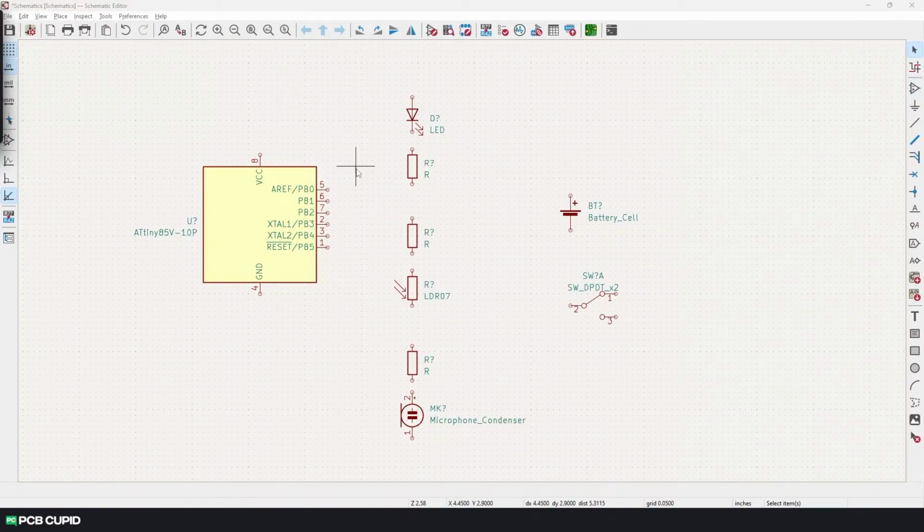You can see the ATtiny85 pinout looks a bit odd and doesn't match the standard convention for numbering from left to right. This is to optimize the symbol on the circuit diagram to make it look neat. Usually, the positive power symbol is placed on the top and the ground is placed at the bottom. And in some cases, they would also group a few pins together for easier understanding.